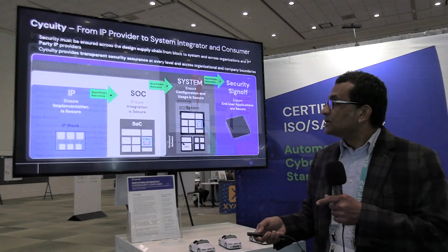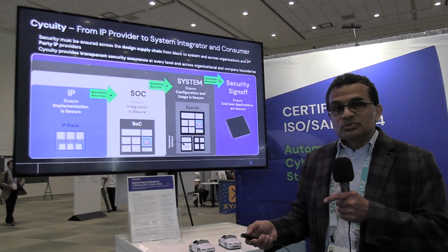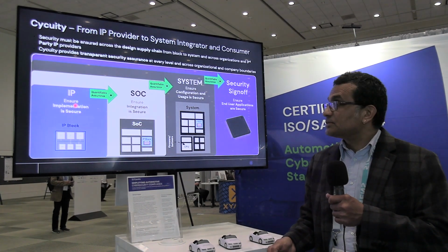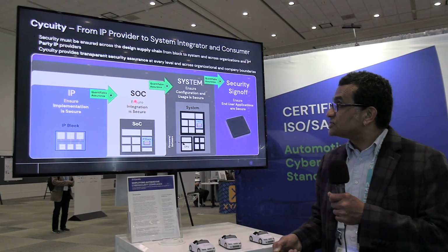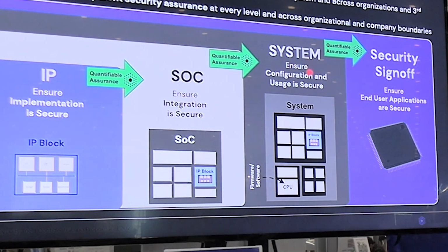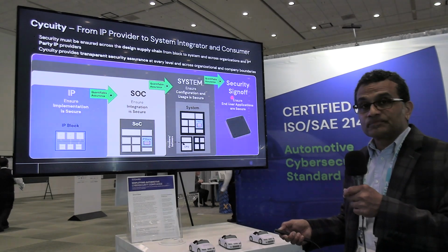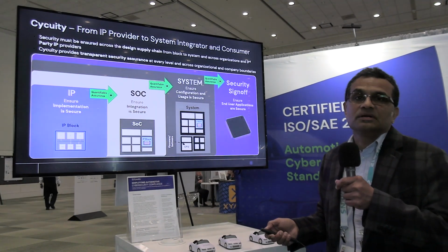Then finally, what Radix does is it allows you to find issues at the block level, then you can use the same rules that we used to find issues at the block level at the subsystem level, and then finally use the same rules as well as add more rules and run them at the system level. So what this allows the user to do is expose issues at every level in your design before you tape out. So it provides a complete solution using information flow tracking to find any bugs or security weaknesses as your security assets flow in your design from block level to subsystem level and to IP level, so that when you finally do security sign-off, you're confident that you are taping out a secure chip.